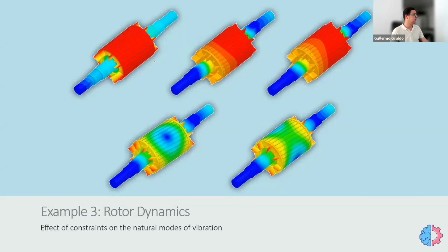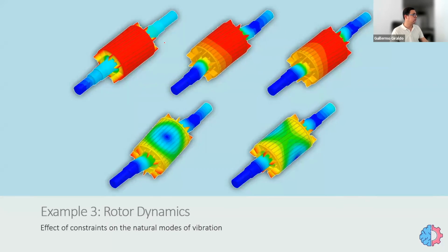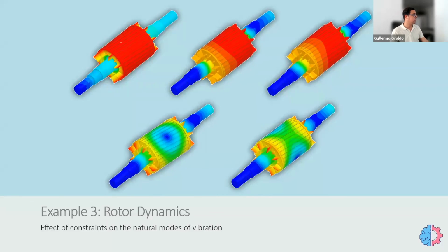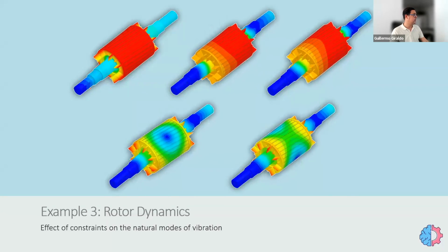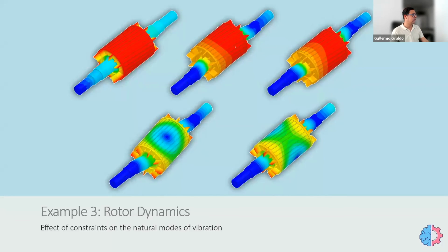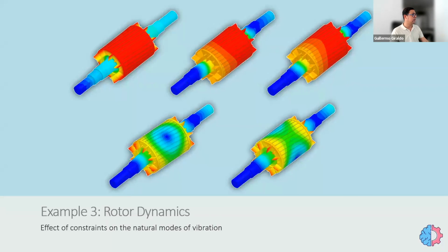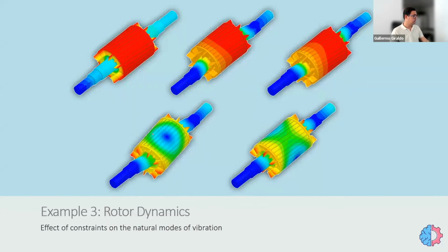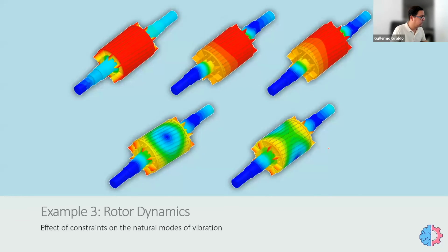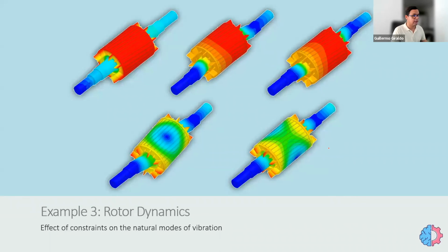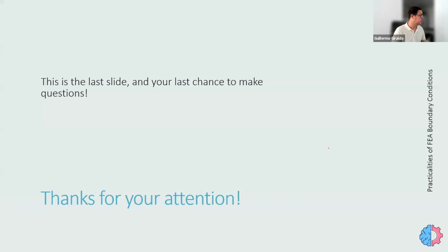And you can see here that by applying these boundary conditions that I just described, we are able to capture all of these nice modes. Torsional modes, you can see with the fix at the end where the power is actually transmitted. Some flexural modes, you can see that the correct lengths are captured in these directions, and all of these second order flexural modes. So very, very important lesson there. And that completes the example.